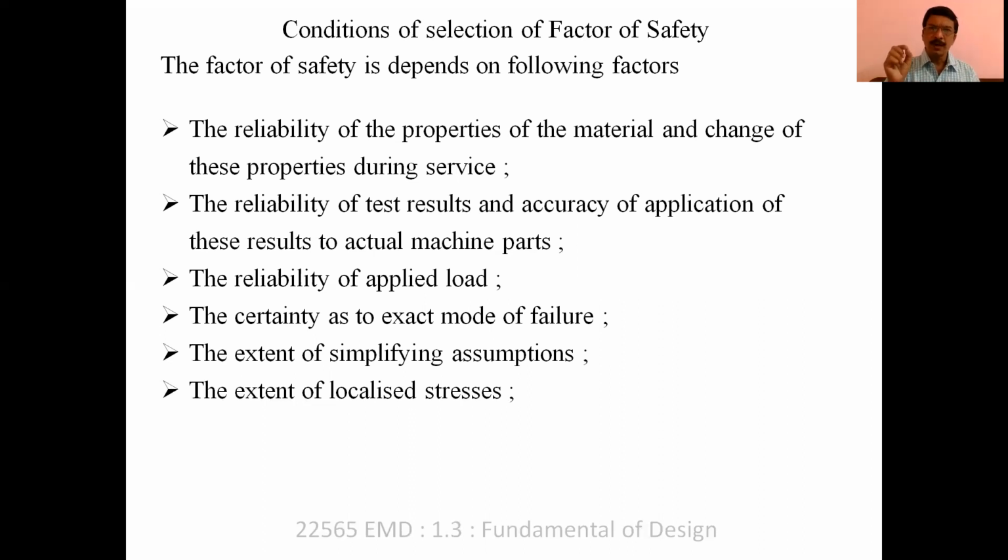Wherever there are localized stresses, meaning a pointed load is there, if there is a pointed or acute load, then you should not go for a less factor of safety. We must consider the safe side, a higher factor of safety. Just like in case of gears, in case of your cam and follower, or in case of your ball bearing. So there are localized stresses.